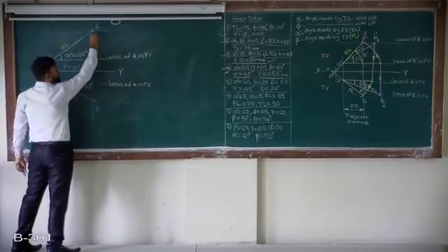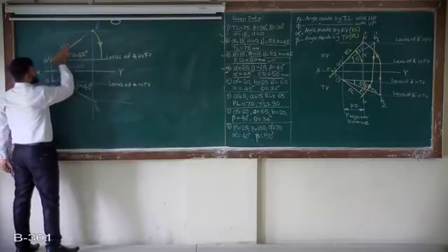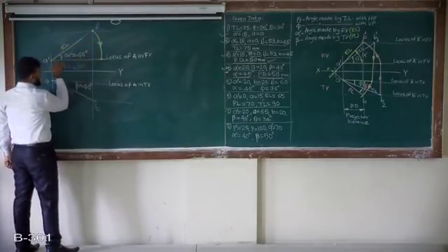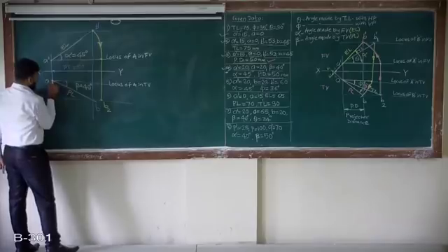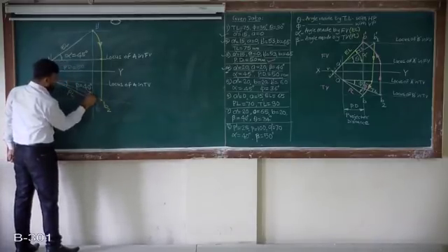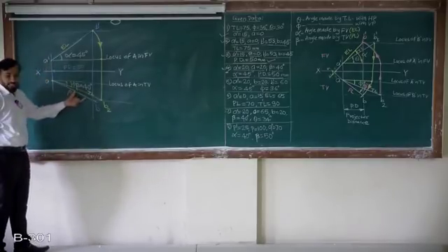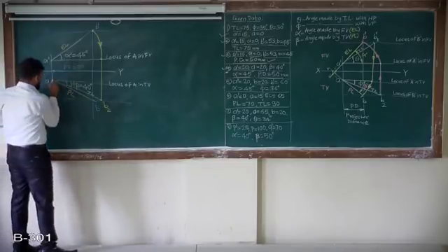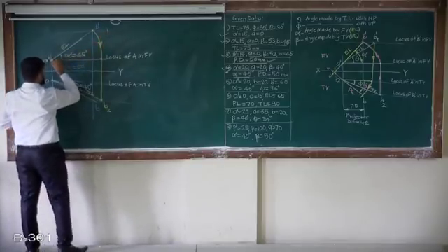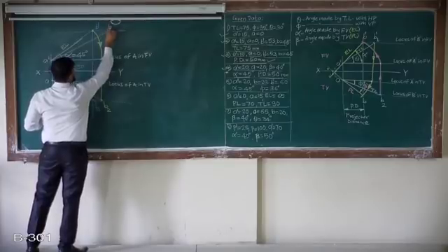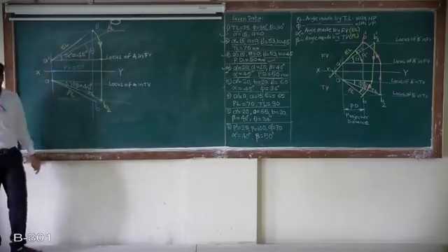So how to get true length in any view? Rotate this. So I will rotate this EL, with A dash as the center and this distance as radius. Rotate up to the A dash and then take projectors. This point is B2. Join with A, you will get this as a true length and the corresponding angle as phi. So once you get the true length in any view, the true length remains the same. Measure this true length, take it in compass from A dash, mark here and join it. This will be point B1 dash and this angle is theta. So that's the problem done.